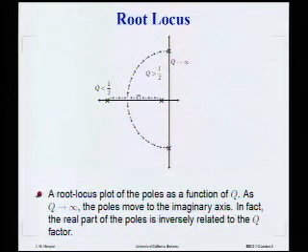On the other hand, if the Q of the circuit is low, below 1/2, the poles go onto the real axis, and the circuit becomes overdamped, as you know from simple second order systems. So if we want a very underdamped response, we should make Q bigger than 1/2. If we want an overdamped response, or minimum damping, we would operate with Q less than 1/2. Of course, damping is just an equivalent way of talking about a circuit in the time domain. Damping and Q are related: damping is basically the inverse of Q, times a factor of 2.